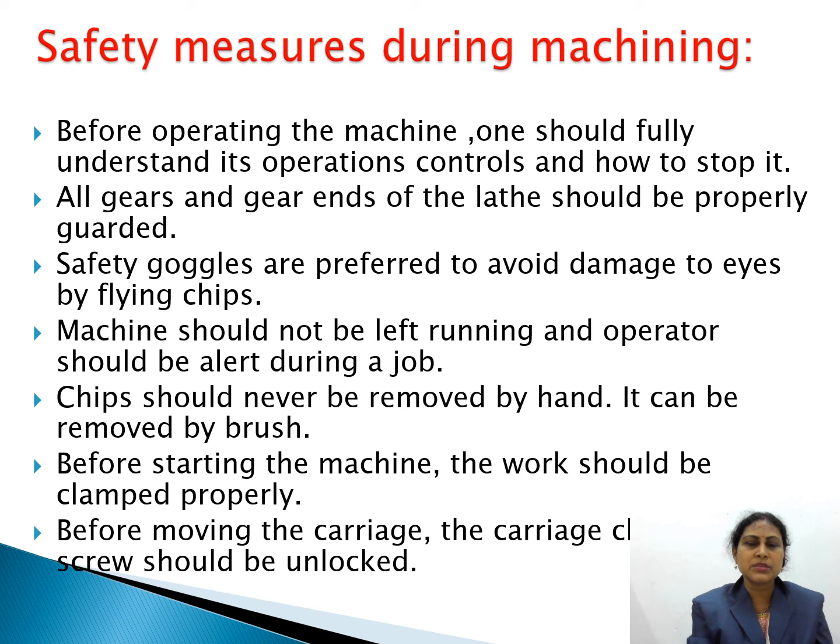Before starting the machine, the workpiece should be clamped properly. Then, before moving the carriage, the clamp screw should be unlocked. So, these are the safety measures during machine operation.